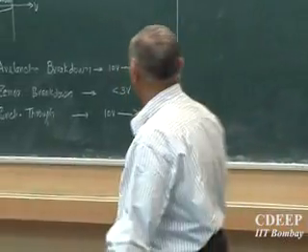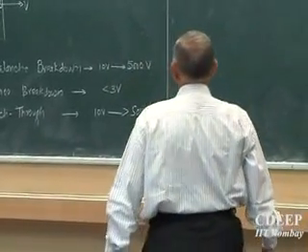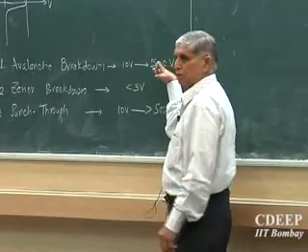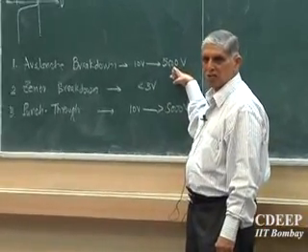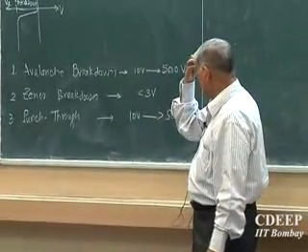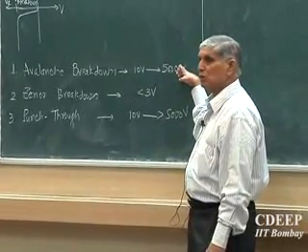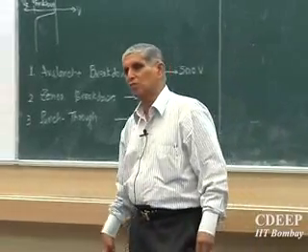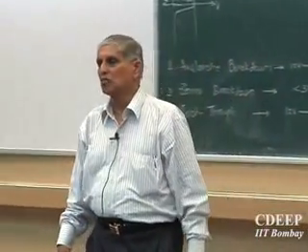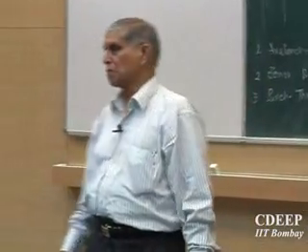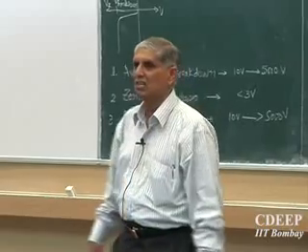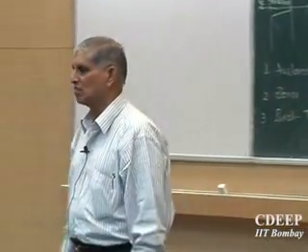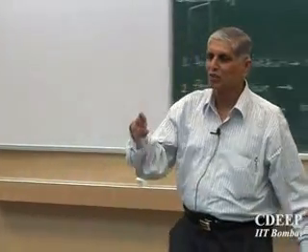So it depends on your requirement of the device, one can find out where you want your breakdown to be. In power devices we need large reverse breakdowns, typically of the order of at least 2000 to 5000 volts, whereas in the case of normal electronic devices 100 volt breakdowns are more than sufficient. 100 itself is a large value, 30 volts is even good enough.